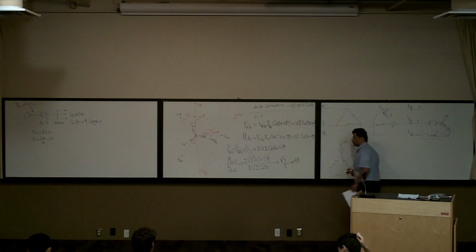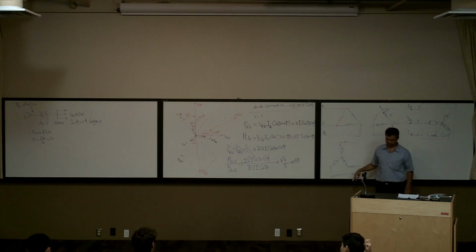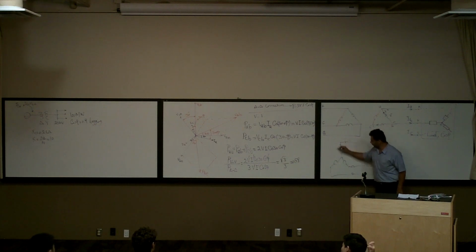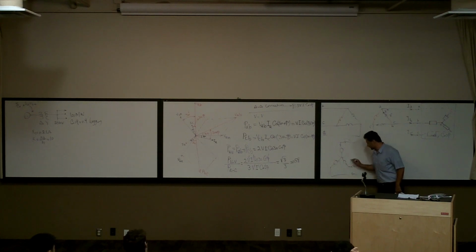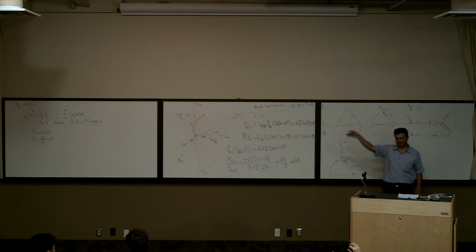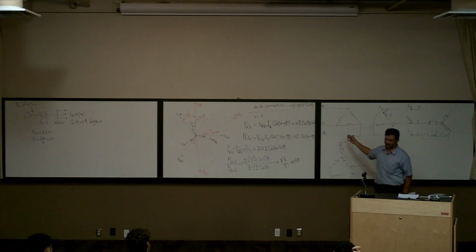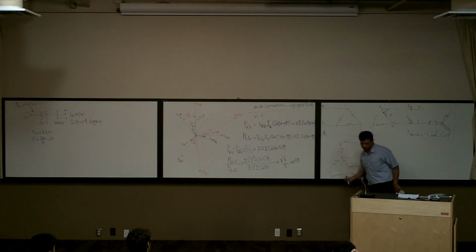See, usually guys, we don't even put R. R is very small compared to the X. This is the one phase of the generator. Every generator has a source and some impedance. This is the second phase. This is the third phase. In this example, I can assume the generator is ideal, which means all these X's are 0, or I can calculate the voltage here. You know what I'm saying?